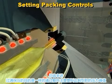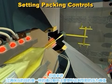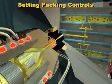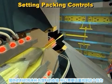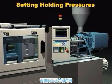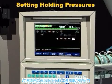In summary, regardless of the packing method that's used, the objective is the same. It is to force additional plastic into the cavities to achieve the desired peak cavity pressure. This compensates for the shrinkage that occurs when the plastic cools, and does it in such a way that the required part properties are achieved. After the mold is packed, one or more additional holding pressures are set to either maintain or decay the plastic pressure in the cavity until the gates freeze.